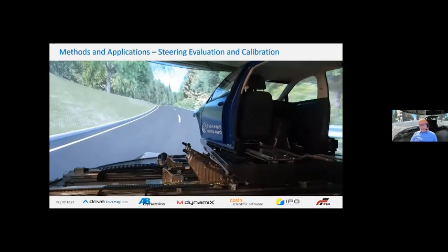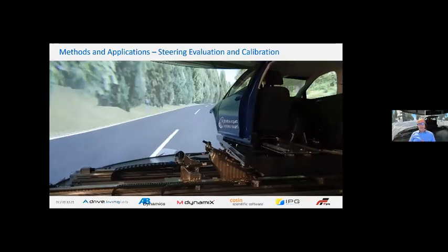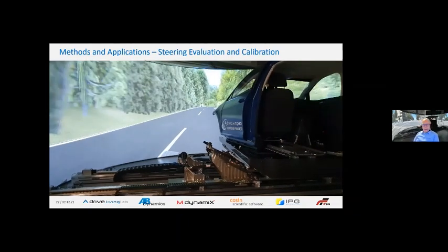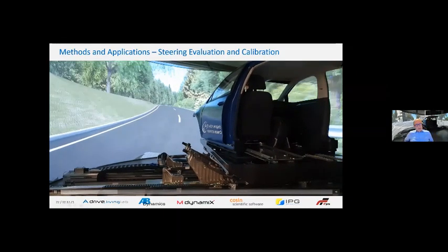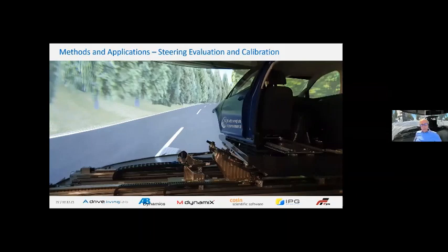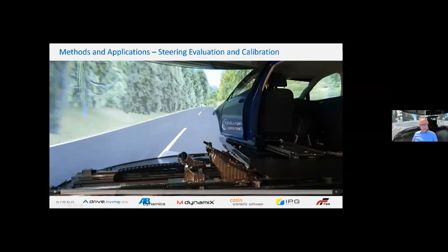And often the case, after they are finished on a straight road, then they go to another maneuver. Some maneuvers are for example slalom or lane change, or also steady circular driving or something else. And the next step is to go to, I will repeat that, maybe a cross-country road. We have certain cross-country roads which are one-to-one digital twins of real roads, and therefore you also see the movement of the body, of the motion. Therefore, we can also test, I would say, the behavior of steering then under realistic conditions out of a proving ground.